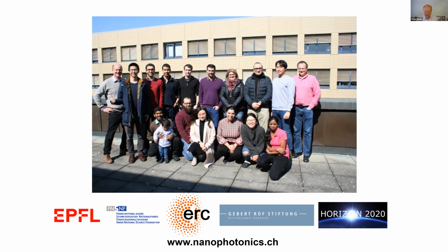More recently, we've been trying to fabricate very high aspect ratio electrodes. So we had nanowires of gold that were maybe 200 nanometers wide and several microns long, and we realized that they were not stable at all. And using metals like chromium, for example, adhesion didn't work. So more recently, what we have discovered is that self-assembled monolayers work very, very well as an adhesion layer. And because they're very thin and dielectric, they do not disturb the resonance at all.